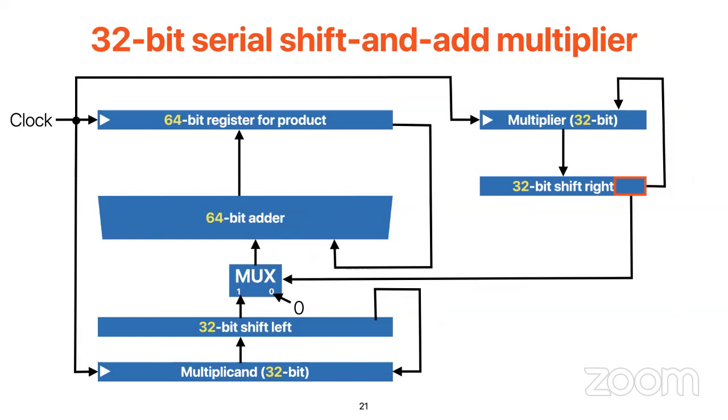But in cases where one path has a component X and the other has a component Y, and there's no immediate way to know, you have to look at both components to see which path is shorter. The reason B is the longest one is that we have 33 gate delays on the 64-bit adder, the shift left by 4, and the register we have to access by 2.